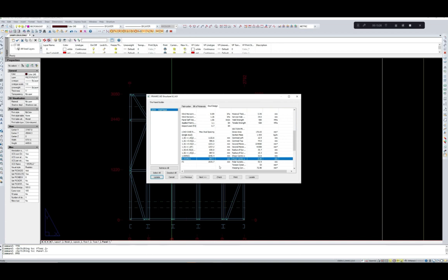manually, because with cement board it has been found that the deflection is reduced by only 30%. So we should reduce the wind load by 30%, not by what the percentage shown here. Here it has been reduced by 58%. Probably it is because there are some changes in the IBC wind loads.